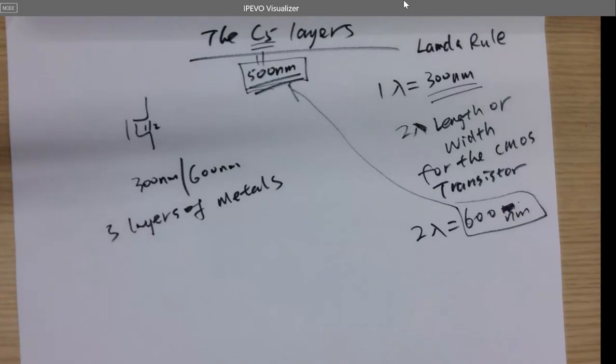So why that matters? What if you're only on 1 metal layer? What's going to happen? Cross it, right? It's going to short the circuit. So that's why our PCB, the ones we have been making, fabricating, or sending out for manufacturing, is 2 metal layers, 1 top, 1 bottom. So you can see the red and blue color in Eagle PCB, just 2 metal layers.